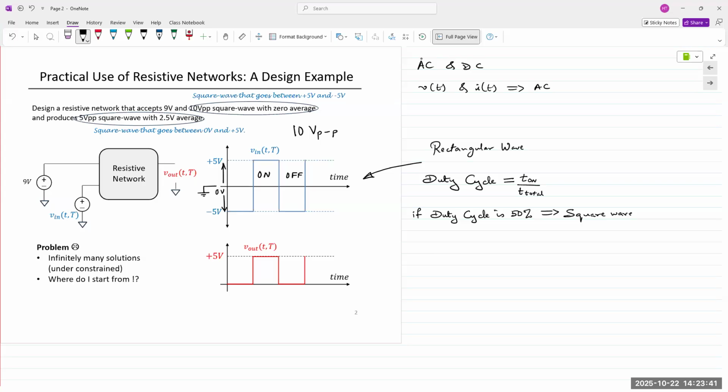Your function generators in the lab, like the ones we have behind us in this room, have a maximum output of 20 volts peak to peak from all function generators that we see in academic environments. That equipment cannot supply more than 20 volts peak to peak. But 20 volts peak to peak is only about 7 volts RMS.